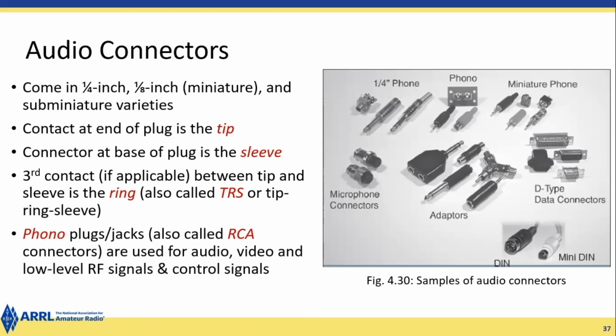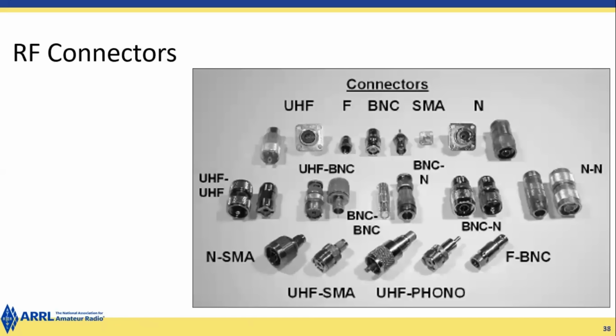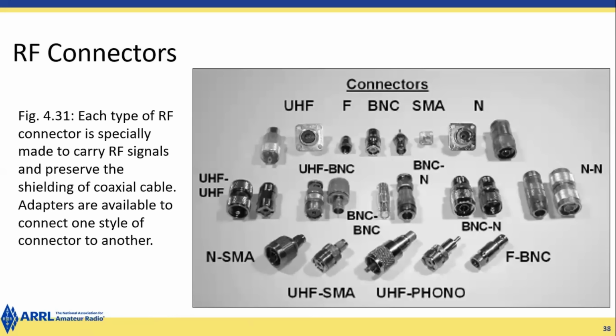Phono plugs and jacks, also called RCAs, are used for audio, video, and low-level RF signals and control signals. Used a lot between your amplifier for your push-to-talk lines. Here are some pictures of some RF connectors. A lot of these are coaxial type connectors. Each type is especially made to carry RF signals and preserve the shielding of the coax cable. Adapters are available to connect one style to another.